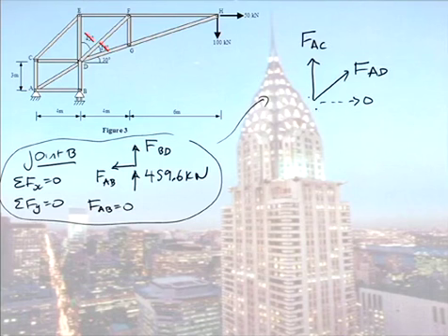Okay? So the force is here. This is a common mistake. The reaction force we got here was negative. That means it's pointing down. So 5% of students would then draw that in the wrong direction. Another 10% of students go wrong by forgetting to put the horizontal reaction in there. So don't forget that horizontal reaction here that we calculated of 50 kilonewtons.